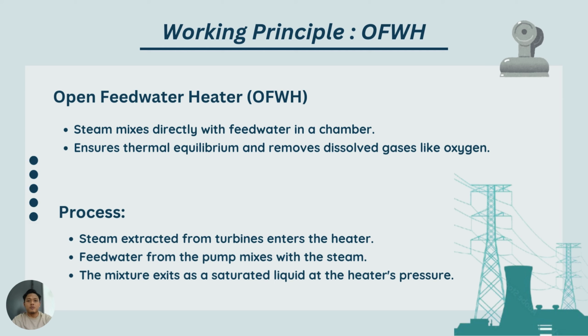So over here is the process. The steam is extracted from the turbine and enters the heater. Then inside the heater, the previously pumped feedwater is mixed with the steam. The result is a saturated liquid that exits at the pressure of the heater. So this direct mixing is the key of the open feedwater heater, making it efficient for certain applications.